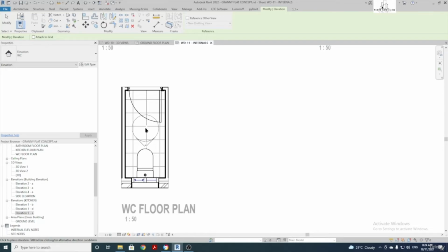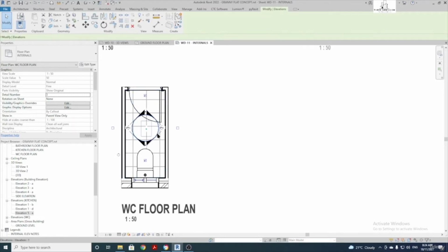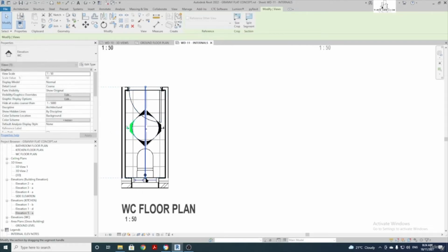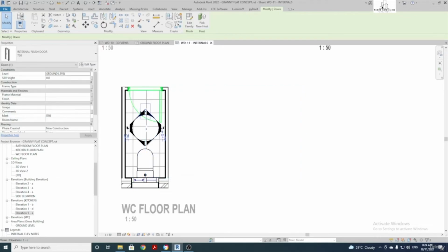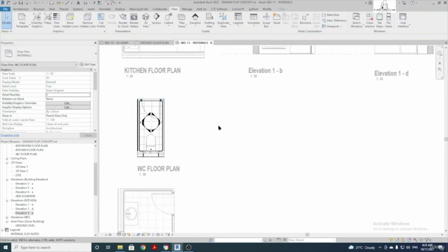So come down here, click WC on there. Now do it for all 4 sides again. So click on this circle, all 4 sides. So create an elevation for all 4 sides here. Again, we can drag out our views here before we drop them in. It's a better way to do it. So click on each one of these arrows and drag the little blue lines out to each side of the walls, like I have done here. We've got all those 4 done.